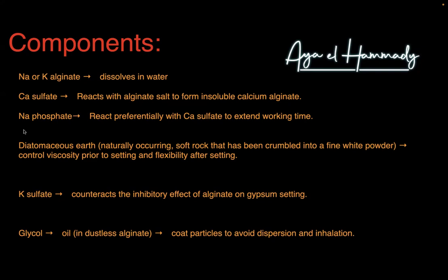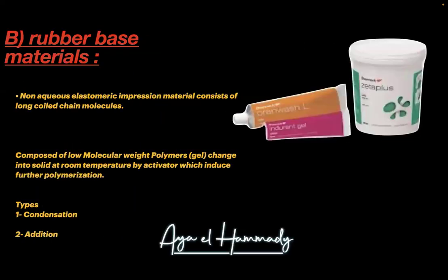What about here, the sodium phosphate, okay? It will react here with the calcium sulfate to extend the working time, okay? Potassium sulfate, it counteracts the gypsum setting, okay? To avoid it getting tough in a short period, okay?